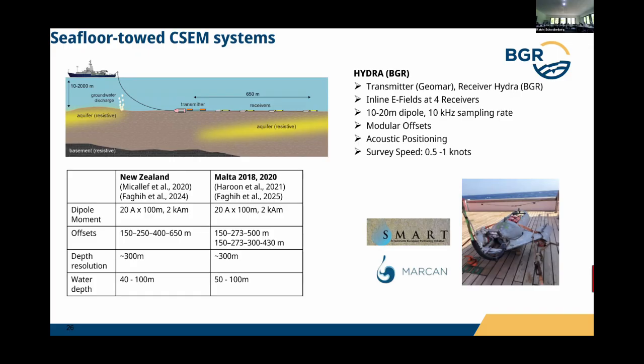We bring energy down, high voltage down, transform it into high current. The transmitter we can operate from the ship. We have different systems. We used to use the streamer behind as a black box. There are data loggers connected to that. Behind each data logger is a dipole, 15, 20 meters long. Each data logger has a high precision clock.